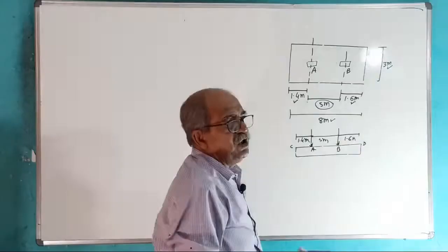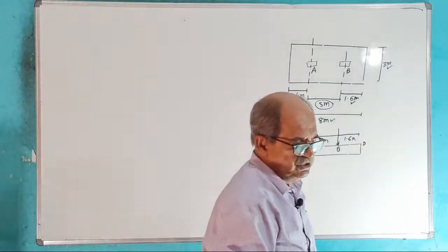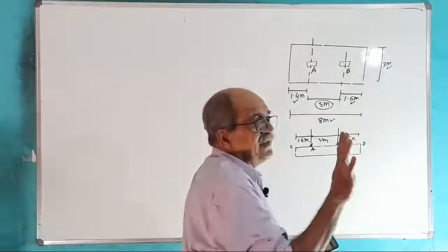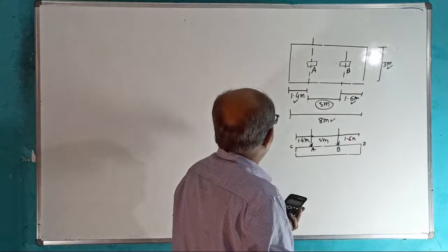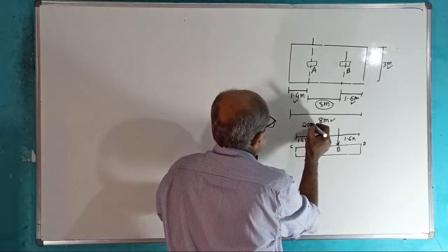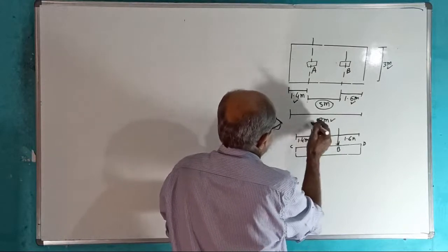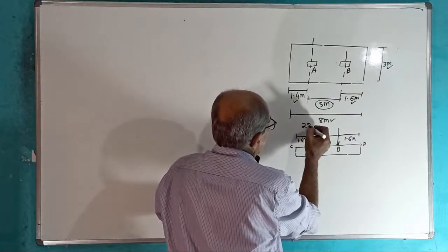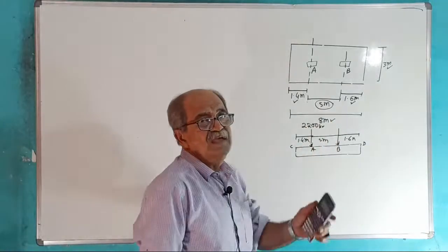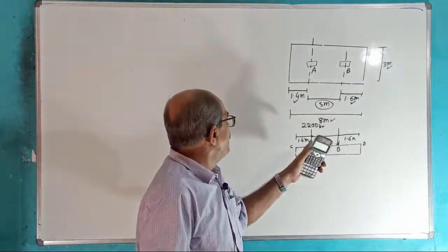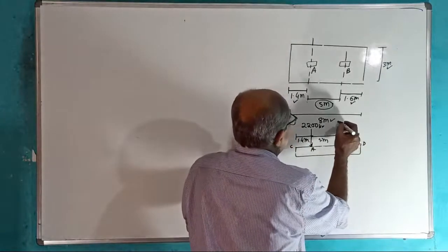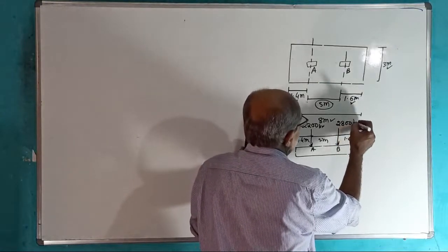Now I require column loads. Just a minute, I should set the column load; randomly I can't give. You don't bother what I am doing. Around heavy load, I will take a load of 2000 kilonewton here. No, little more. I want to round it so that the total is a multiple of 5. 2200 kN here, meaning the load of the left column is 2200, and the corresponding load here is 2800 kilonewton.